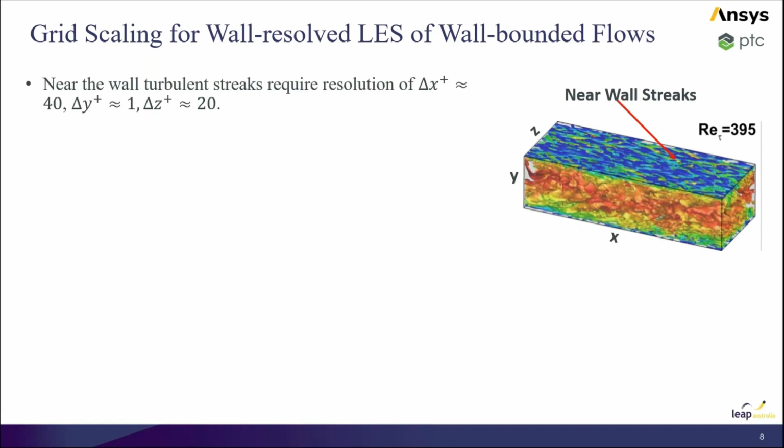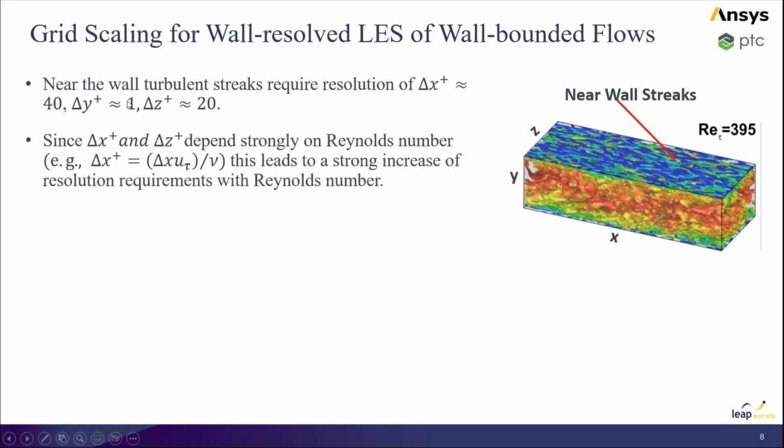Because of resolution constraints, things like these channel flows have been examined with direct numerical simulation, and so grid requirements for LES can be rigorously established by comparing with those results, setting some guidelines as to how fine the mesh must be. Not just normal to the wall, but along the wall and across the wall. We can't do anything in 2D in LES, okay? So we've got to have enough resolution across to build all these structures.